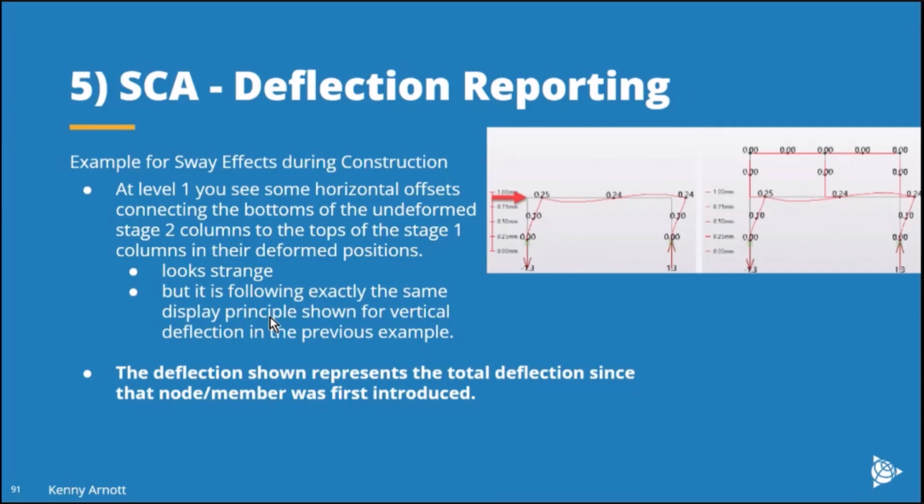This is not as comfortable to accept as the gravity loading case, but actually the principles used are the same in both situations. And the key thing to take away when you're looking at deflection diagrams is that the deflection shown represents the total deflection since that node or member was first introduced.